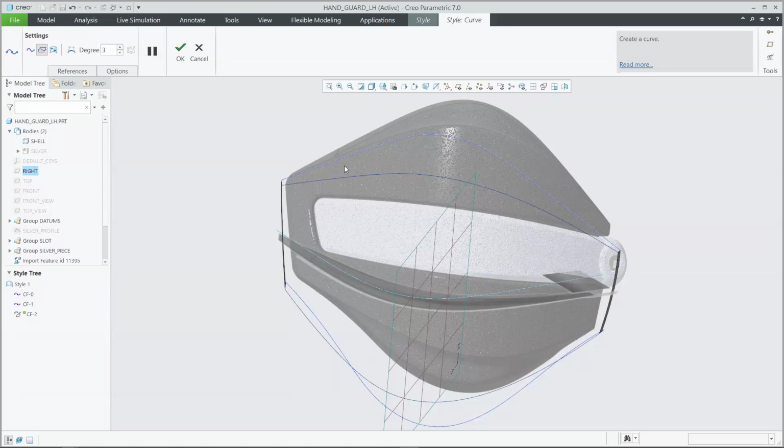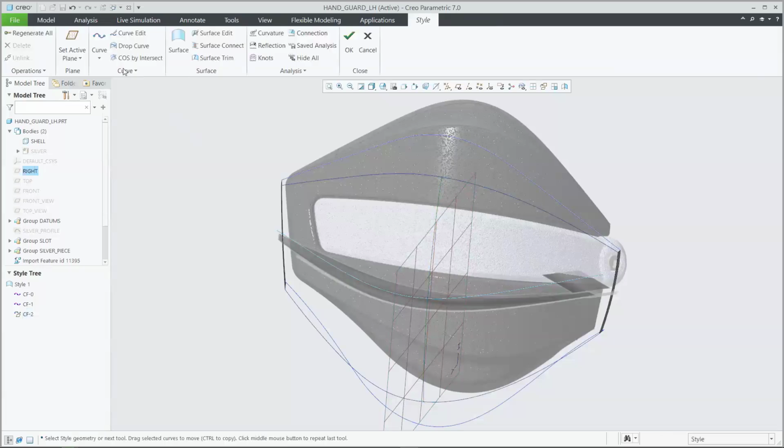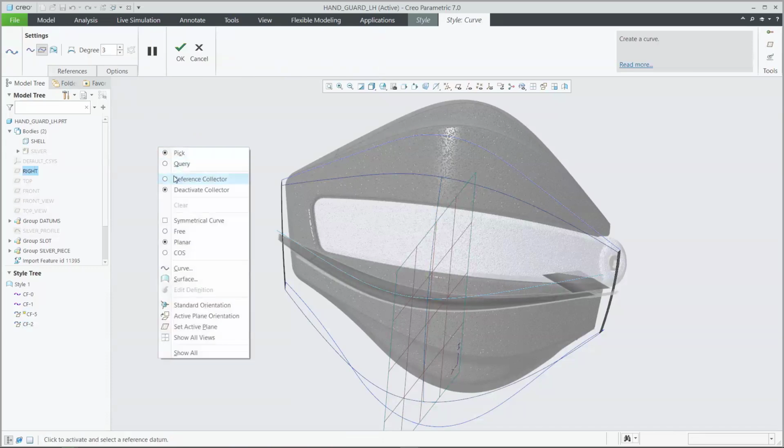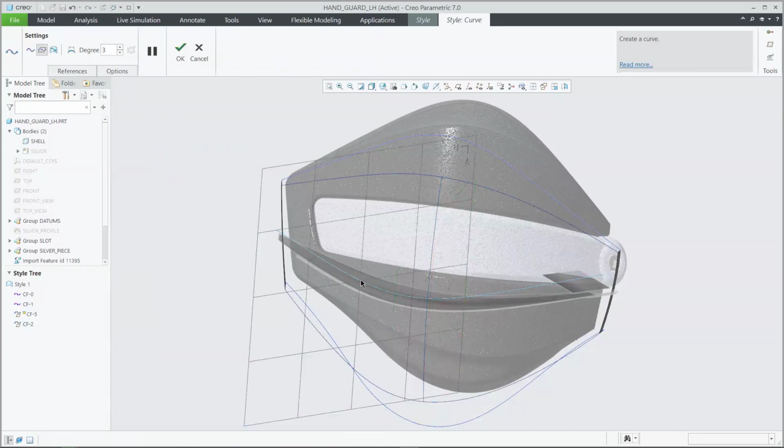And for the curves, we were working with freeform initially, but we can even do curves on planes. So this will ensure that if I already have some sketched outline or a skeleton or copy geometry from a model that I brought in, or geometry that I'm associating with an assembly, for example, I can use those to be my control curves and then design the curves, in this case the direction of where my cover is going to go, on the specific plane that I want. And I can manipulate exactly where my points are going to lie on my plane based on those curves.